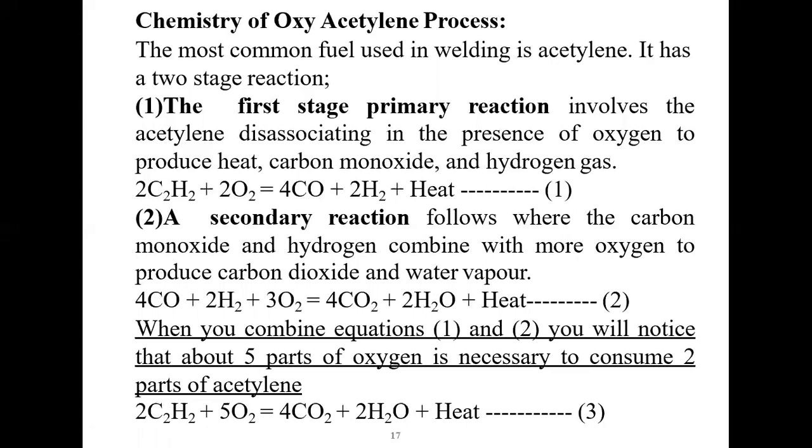Okay, and it will help for our welding, and it is the primary requirement for our oxyacetylene welding. Here is also a statement that I want to highlight: when you combine equation number 1 and 2, you will notice that about 5 times of oxygen is necessary to consume 2 parts of acetylene. That I have already told through the equations.